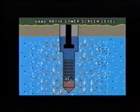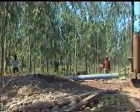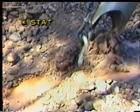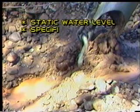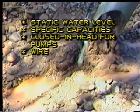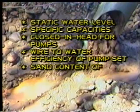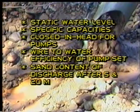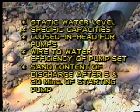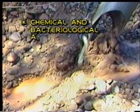In case sand gets accumulated up to a point in the well where it enters into the screen, this should be bailed out and cleaned before taking measurements of static water level, specific capacities, closed-in head for pumps, wire to water efficiency of pump set, sand content of discharge after 5 minutes and 20 minutes of starting the pump, chemical and bacteriological analysis of water samples.